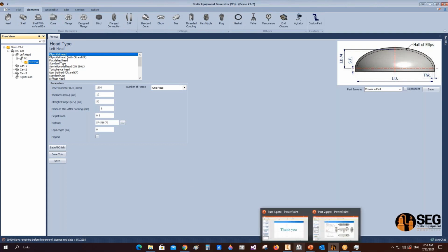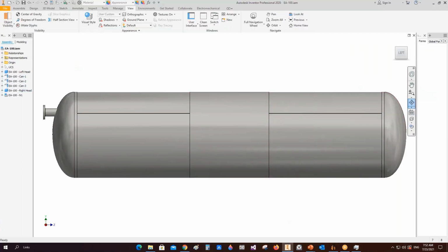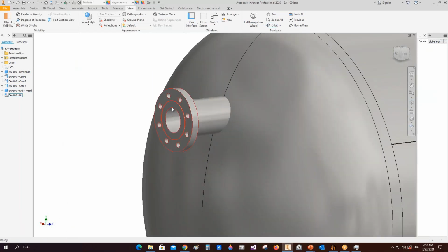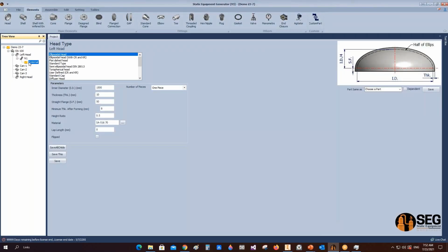So you can connect another point or other elements to the facing of this flange. You have an external connection here, so you can connect anything here, like another flange, a gasket, or the elbow. So you can connect anything to the end of this elbow by selecting the external connection and adding another element.